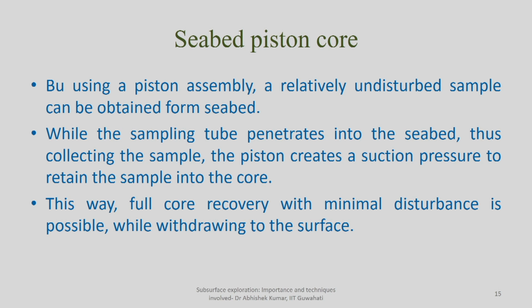Then seabed piston core, by using a piston assembly. In this particular case also you put the sampler into the seabed by means of a cutting shoe at the bottom, but the beauty in this case is in the withdrawal of the sampler.